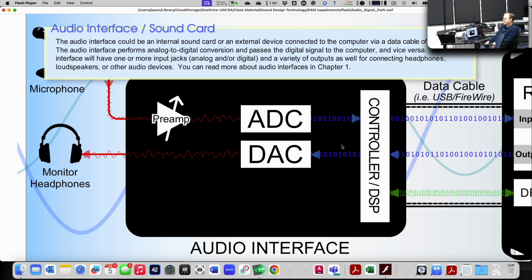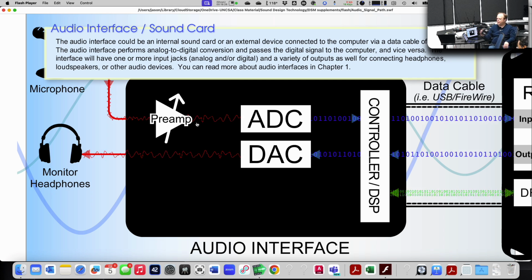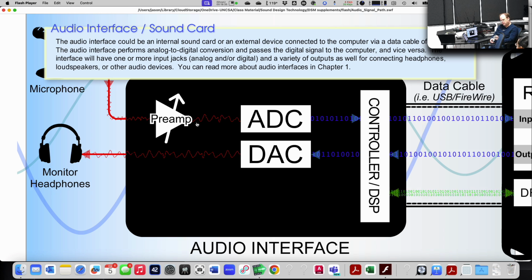Okay. So what's inside of this audio interface? Well, it kind of depends. The main thing that you're going to notice is the number of inputs and outputs it has. So like this one that I'm carrying around here has, looks like two inputs. There's a third one here, but I think it's shared. It's a shared circuit. So 2 inputs on XLR connectors or 1/4 inch. And the third one is like an instrument level input, so you can plug a guitar straight in. And I think that routes through like number 2 or something. And then it has 2 outputs that are on balanced 1/4 inch.